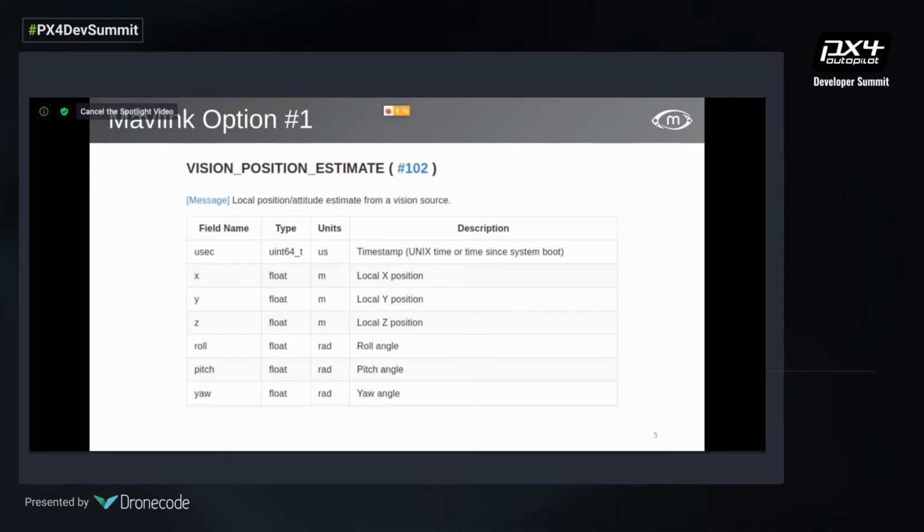This is the first one that you'll see in the PX4 odometry documentation page. And it's extremely simple. You're just sending in the drone's position relative to the local frame in X, Y, and Z in meters. This is going to be like the NED coordinate frame, north, east, and down, or since this isn't necessarily lined up with north, it's more appropriate to call it the local frame aligned with forward, right, and down as the odometry system is when it boots up.